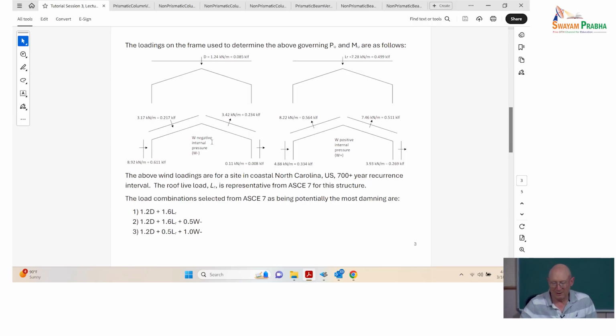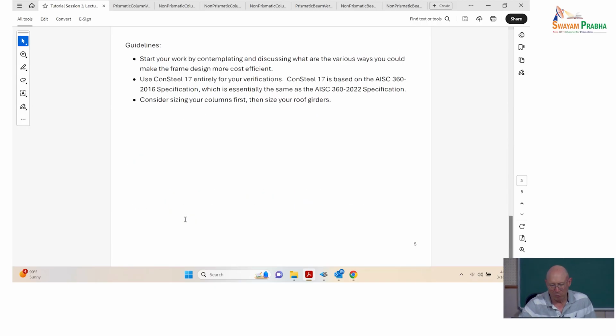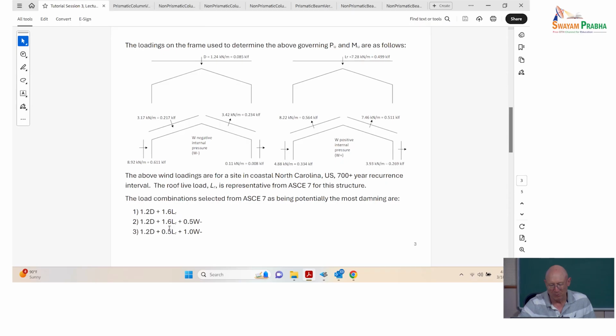And so if we take these, I guess I had one load combination jump to the next page here. So we're going to do ASCE 7 load combinations. A common one, pretty much your maximum point-in-time live load, is the first load combination. So that's 1.2 dead plus 1.6 live in ASCE 7.